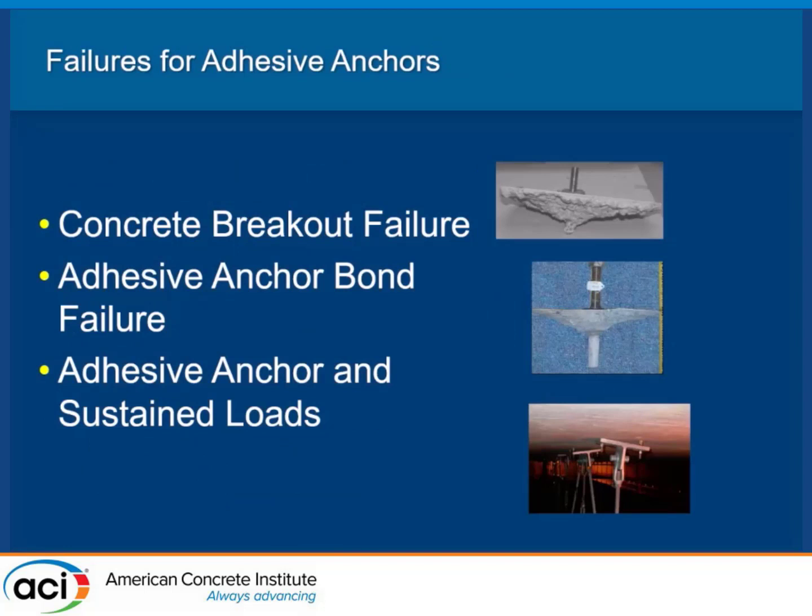And then, of course, adhesive anchors, we already kind of got into that a little bit. You know, a bond failure is by far the mode, if these things fail, they're going to fail in bond.